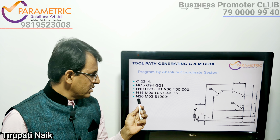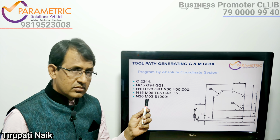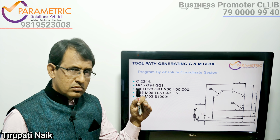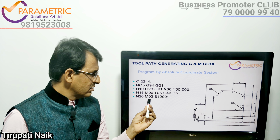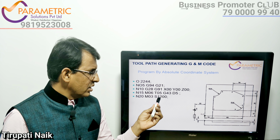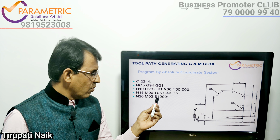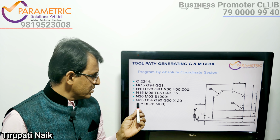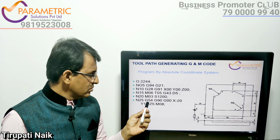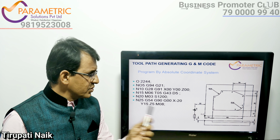Now the next step is block number N20. The spindle rotates in the clockwise direction, that is M03, and the spindle speed is 1200 RPM. The next step is N25. G54 is the workpiece zero.